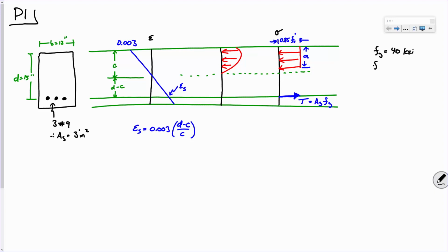We know f'c, right, the compressive strength in the concrete, and that is, what's that? No, it's not 30, it'd be 3 ksi, because we have to divide by 1,000, 3 ksi. If we could craft up some 30 ksi concrete, I'd be a millionaire. Actually, no, there is ultra-high performance concrete that can get in the 20s, but that's another topic for another day.